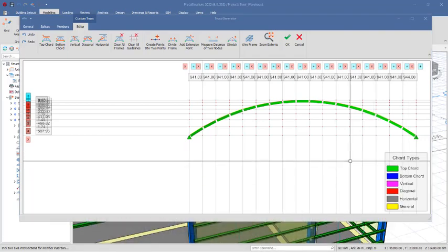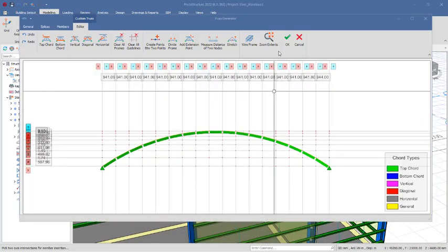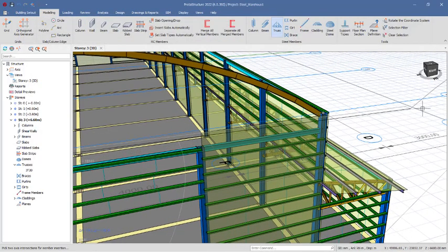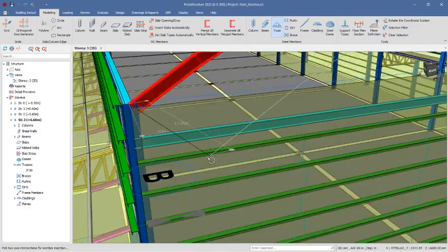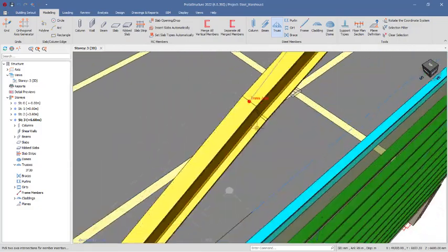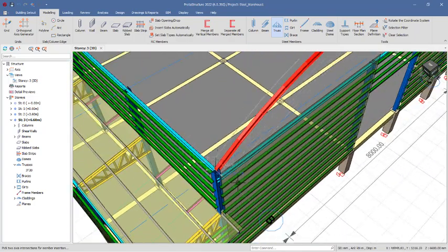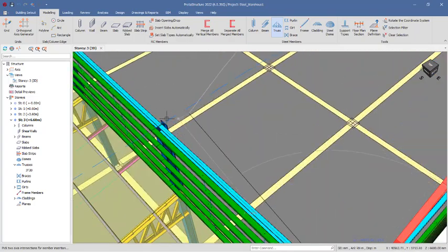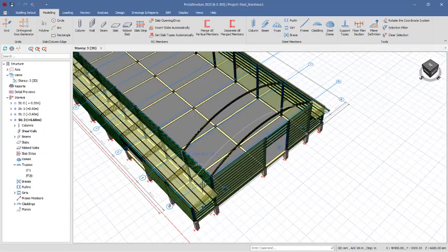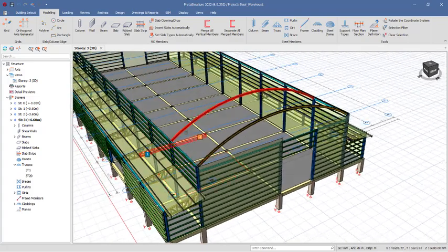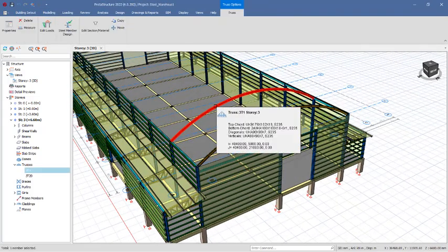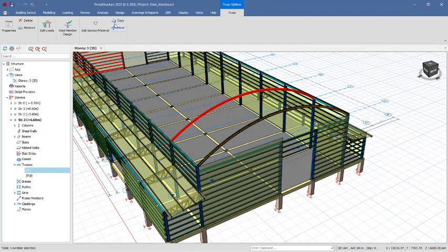So I will minimize that and click on the OK option. Once I click on the OK option, you can see what I'm having right there. So this is the I-beam here that I have, okay, just like this, all right. So if I want to continue to place this I-beam, I can just continue to place it just like this, okay. Or if I deselect it, the first method, if you deselect it, copy is an issue, but this one, if you select it right there, if you check over here, you can see copy options.